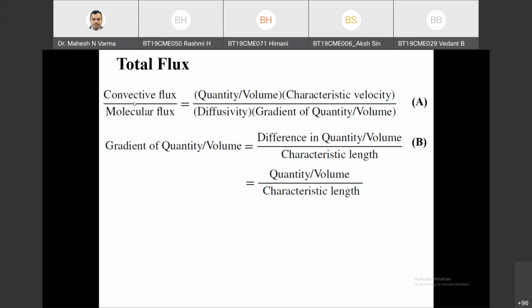There we take the system properties: whether density is important, viscosity is important, velocity is important. Accordingly we derive the dimensionless number involved in that system. Here we are going into the fundamentals of the system and approaching the dimensionless number. The Buckingham Pi theorem is a universal method, and this is subjected to the situation.